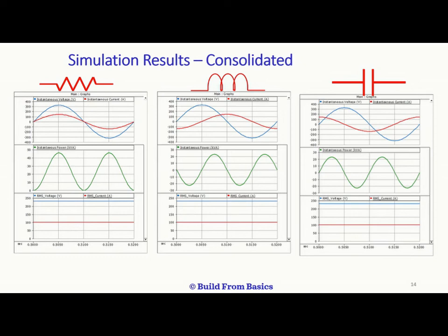So all these elements, that is resistor, inductor or capacitor, equally load the transformer and the AC generator which is supplying the energy to them. Only the resistors perform real work and consume energy. Inductors and capacitors don't do any work and don't consume any active power.